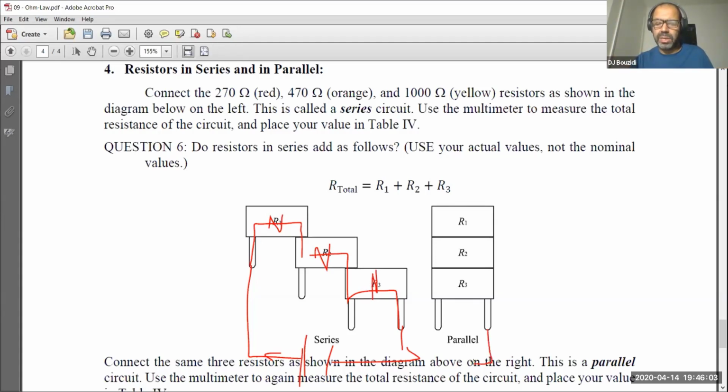Or what I can do is connect the battery in here to this setting. The current comes in here and splits itself between this resistor and comes down, or this resistor and comes down, or this resistor and comes down. In this configuration, what you have is a parallel configuration: 3 resistors, one on top of each other, parallel to one another. The current in one resistor is not the same as the current in the other resistors. Let's say, for example, 10 charges leave the positive terminal of the battery, they come in here, and they have to decide. They cannot all go in one direction, so we say, okay, 5 of you go here, 3 of you go there, and 2 of you go there. When they come back, they all meet again so that they come back to the battery: 10 left, 10 came back.